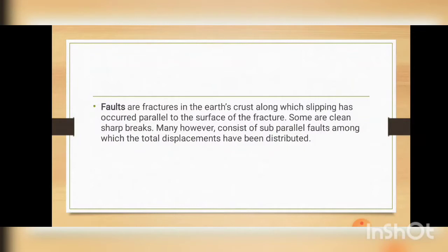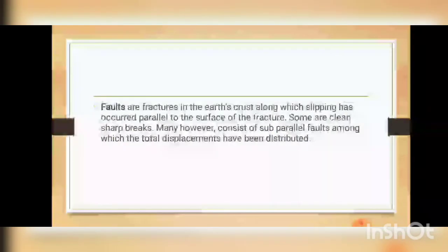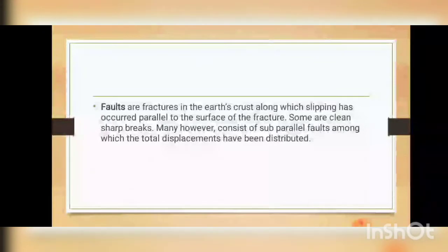Other faults, due to the frictional effects of rock masses sliding over one another, break or crack the rock on either side of the rupture. Some faults pulverize the rock in the fault zone to a clay-like powder called gouge. By convention, the surface of the rupture along which relative movement has occurred is termed the fault plane. The surface in most cases is warped, curved and irregular, and hence the term fault surface is preferable to fault plane.